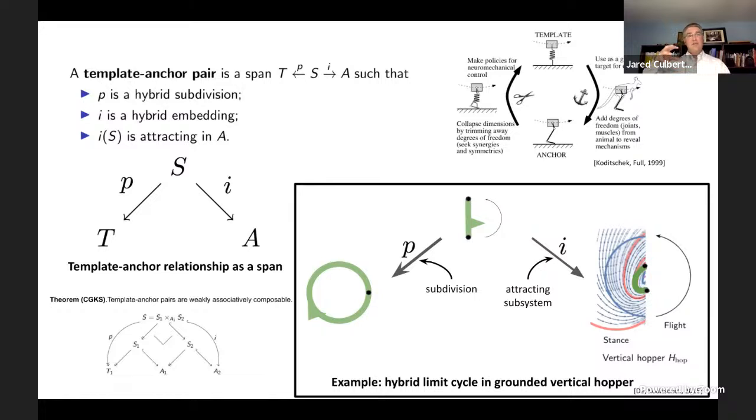And then it has a flight mode, where the only thing acting on it is gravity. And so you can model that just as a reset map, because once it's in the air with whatever state and dynamics that it has, it's going to be deterministic where it's going to land, or what state it's going to land in. And so you can model that in that way. And so we're able to think about the low-level system as just this periodic orbit that you're continuously traversing.